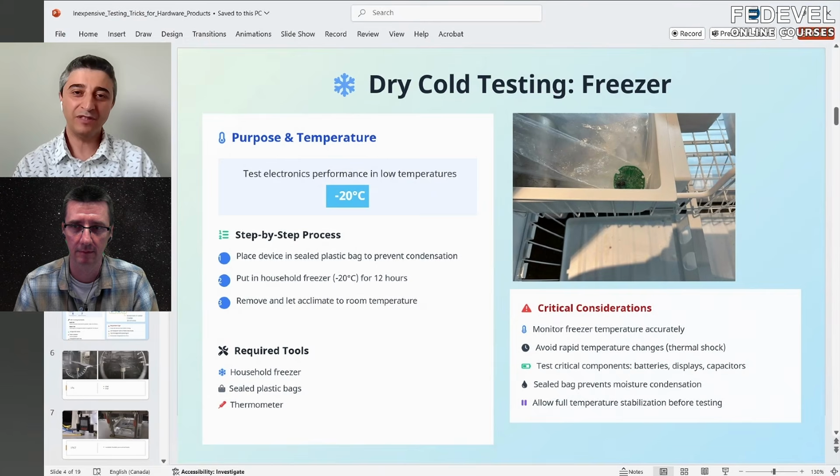Another thing is the enclosure design. For example, in the extreme cold weather conditions in the Canadian market, especially if it's industrial, if we have to choose between a polycarbonate enclosure and a steel one, we will go for steel. The reason is if you're doing a service or you need to drill a hole in an industrial enclosure, if it's plastic, then good luck. The moment you touch it in the cold, it might just shatter all the way.